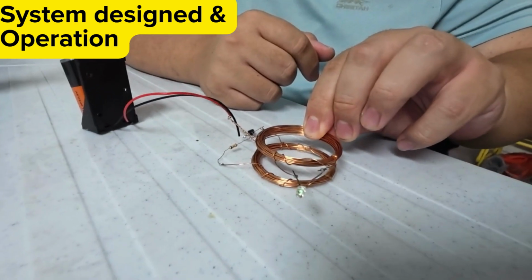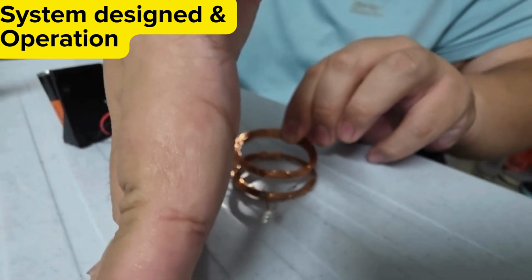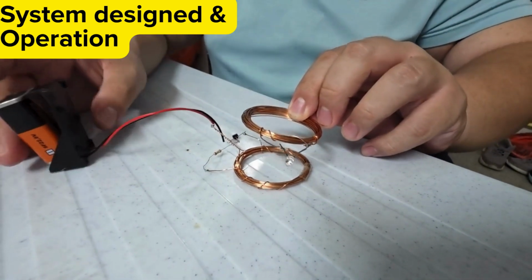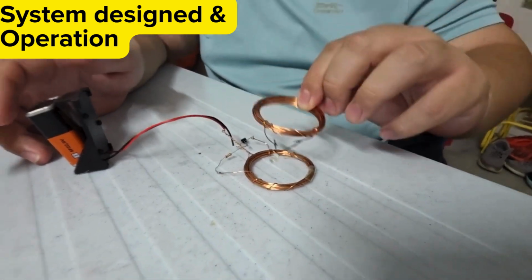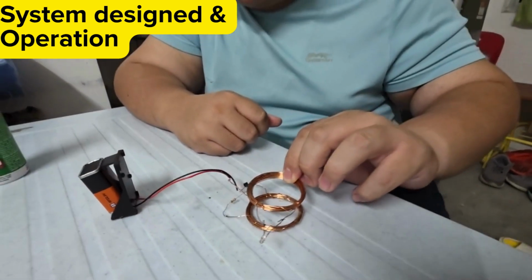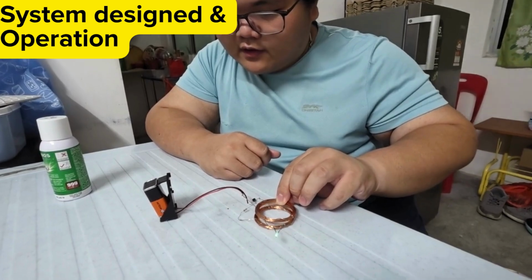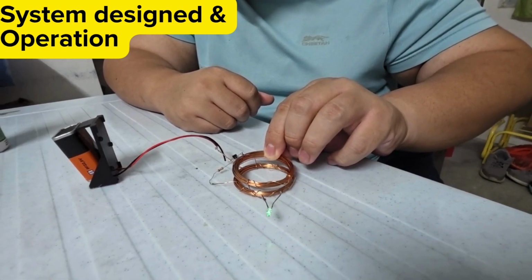As we can see here, the LED is lighting up without the coils touching, and this indicates that our prototype is working. The LED is not lighting up very bright because we only have one battery and we have been playing with it a lot, so the battery is running low. The maximum range that we can reach for now is 3 to 4 cm, and it is brightest when the coils are not touching but very close to each other.